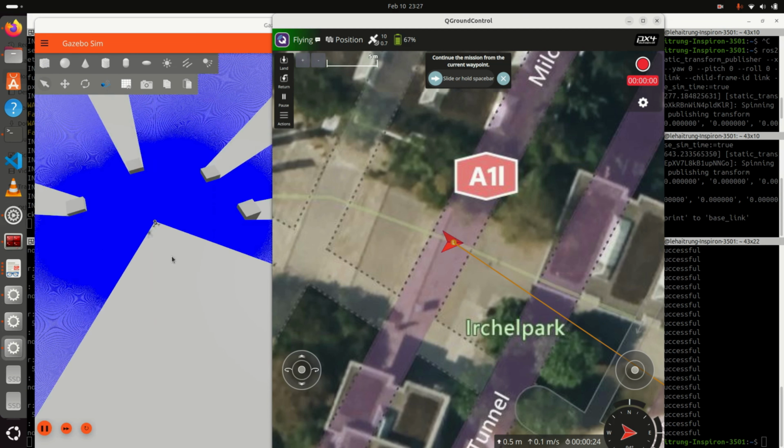And now we are going to turn on the SLAM. SLAM is going to connect the map and odometry, and also make the mapping appear. Because if you put the fixed frame into map, you will see nothing at all, because it's disconnected from everything. It's isolated. So odom is the best friend now.